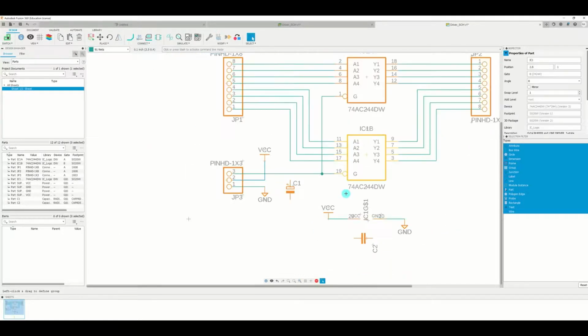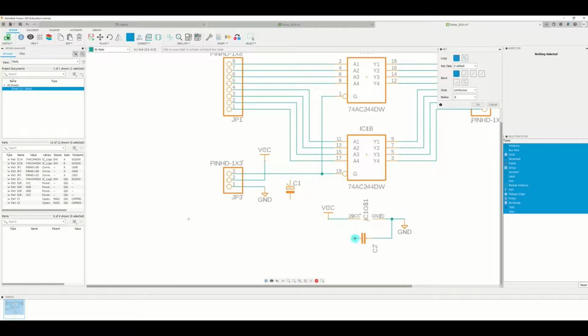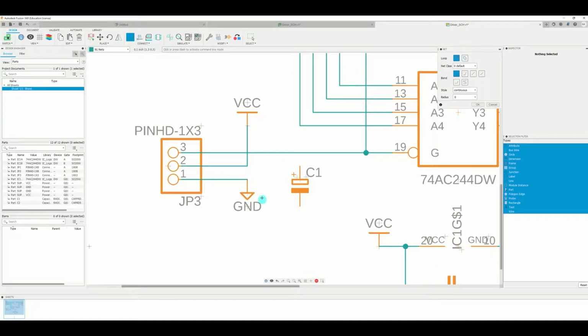You can zoom out like that. So we now connect the ground and the VCC. Select the net, click that one, and then click connect the other one, or you can connect here if you want. Now for this one we can move this down so that we can connect this pin, or you can rotate this. So let's try to move.